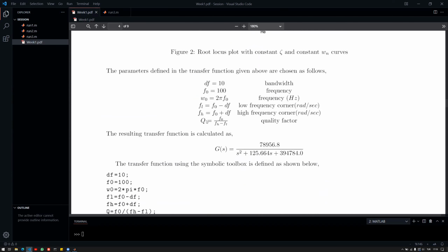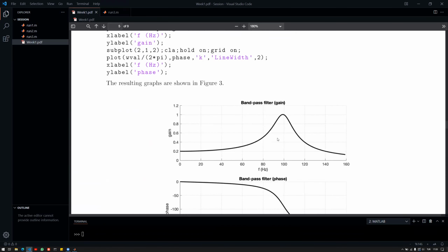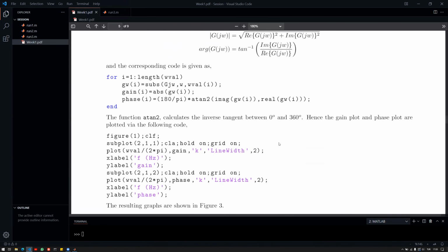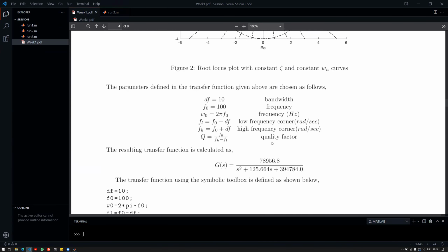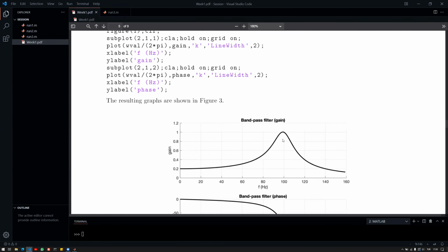properties. So in the frequency domain example, in the Bode plot example, I've chosen a bandpass filter because that's quite interesting to analyze. And it has bandwidth, which will be obvious if we look at the Bode plot itself. This is the bandwidth, basically. And then we have some quality factor. Again, this determines this width here.